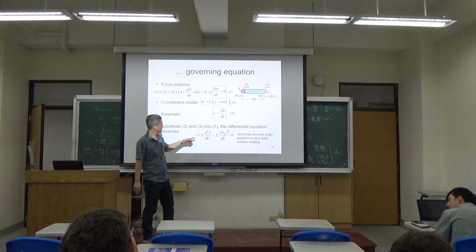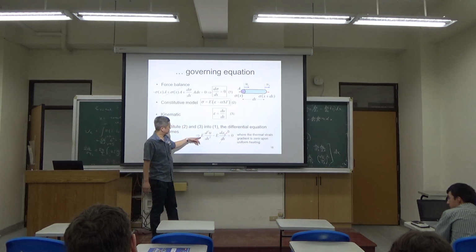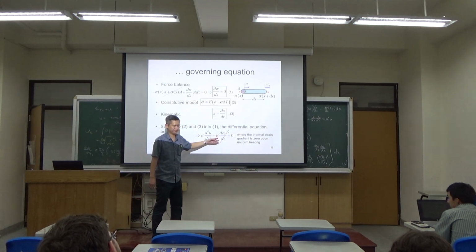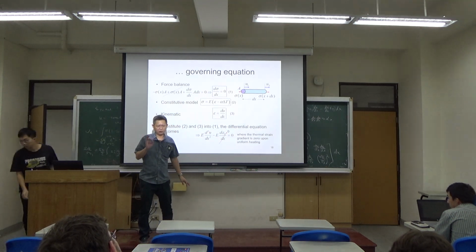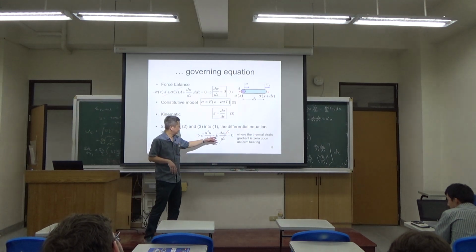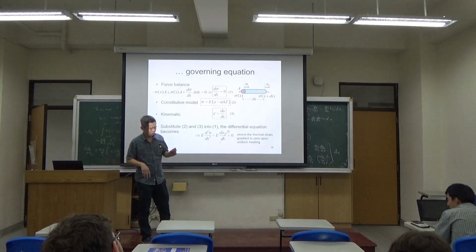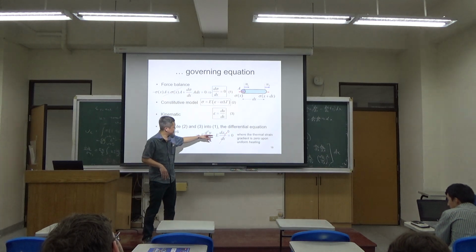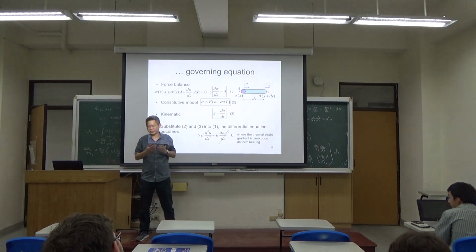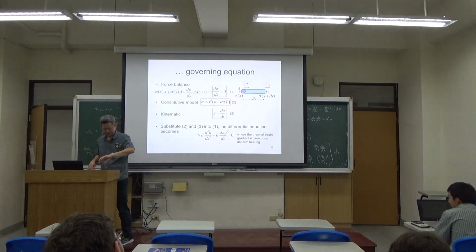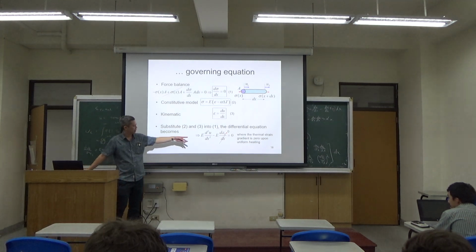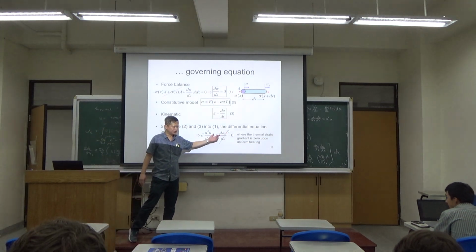obtain the equation which is the second order derivative of displacement plus a strain term. If the strain is varying along the length, then this term is non-zero. But for finite element simulation, you usually assume constant strain throughout the element. So this is a sort of simplification.